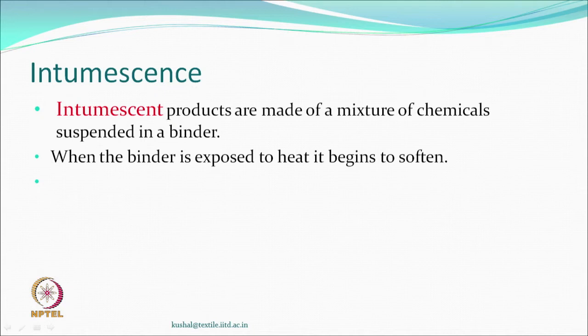So, this compound is a mixture with a binder, and when this binder gets the heat because of the burning, it will get softer and will start, in some sense, let us say, melting, and the chemicals which are there will start reacting and may start releasing gases. So, foam can be created. Now, this foam, if it is a carbonaceous product also, as the carbon keeps burning, will insulate the polymer from the heat.